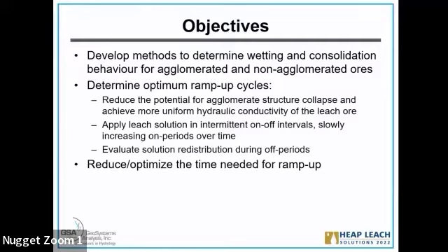And we want to apply solution in an intermittent way, like on and off. What happens is that if you put a small slug of solution down, it imposes a very small impact on the ore, and it will not wet too much, then it uses the capillarity force in the ore itself, and they pull down more evenly.